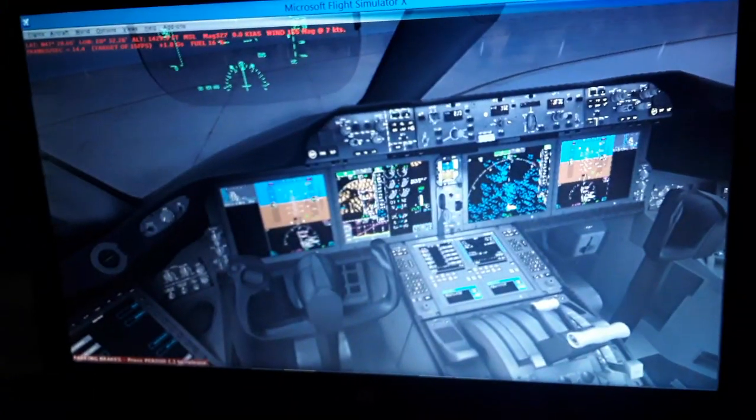So you can see also altitude constraints. Then we have the top of glide to the cruise level, the remaining waypoints and fixes, then the top of descent, and the STARs, the standard terminal arrival routes and waypoints. After the descent, we have the approach, the long final and the short final approach, horizontal and vertical navigation fixes, and altitude and airspeed constraints. It is going to align us with runway 14 at Zurich International Airport.